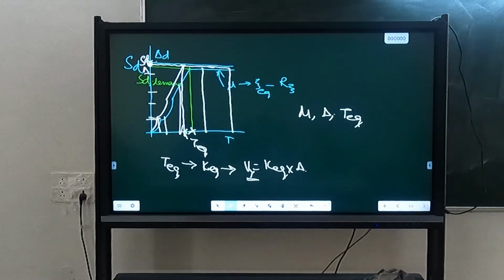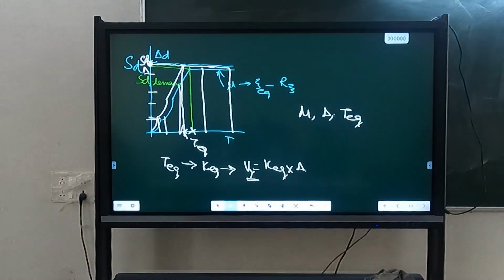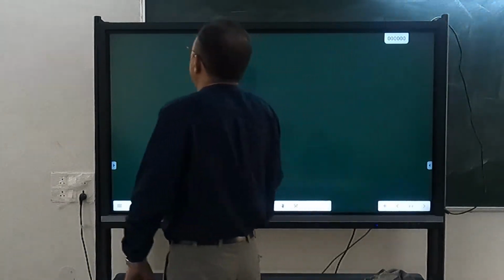Alternatively, if you don't want to use DDVD, you can start with code design, complete the code-based design, and estimate its performance using the pushover method and performance point estimation. You see whether your criteria are satisfied or not. If not, revise it. That is another possibility. So somehow you have to have an initial design. DDVD is only to help you in that. Now we have discussed only pushover analysis so far.